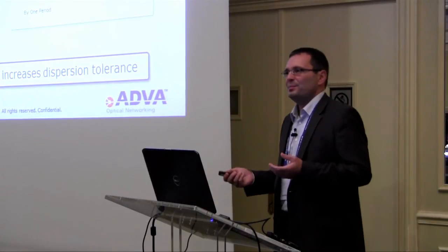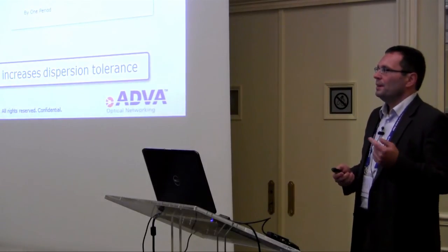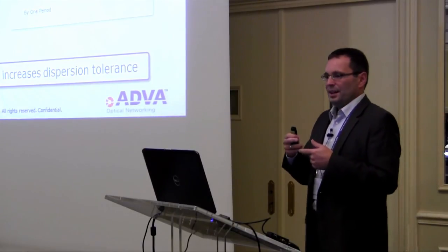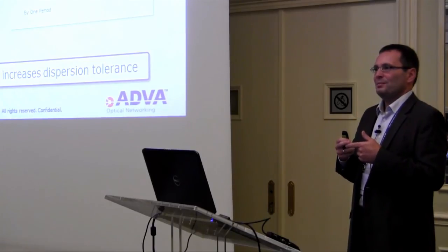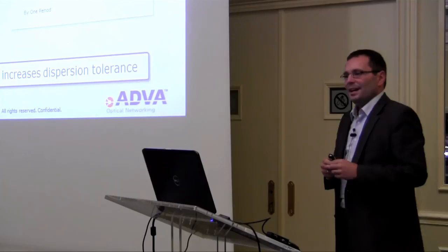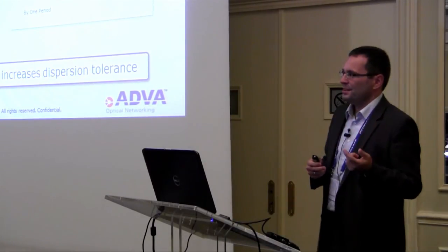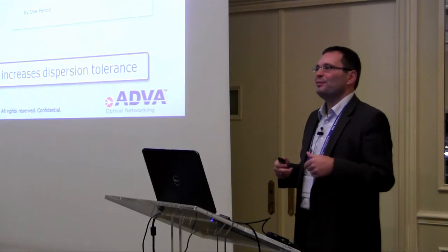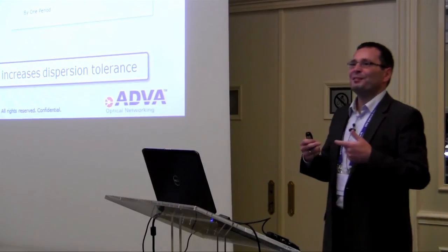Coherent detection is a very simple thing, because you produce the same signal at the receiving side. You superimpose it to the signal you receive. And it has 2 fantastic benefits. The first one is you can detect the phase changes, because if the phase changes, when you compare it to your signal, you can see that. And second, if you modulate the signal with the same frequency over your receiving signal, you're canceling out all the other frequencies, and you're amplifying the frequency you want to see. So it acts like kind of an amplifier.